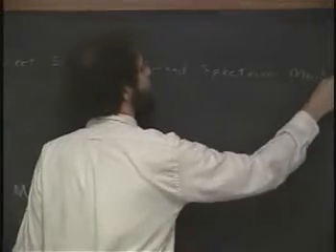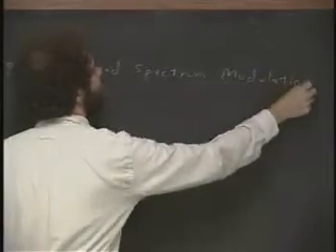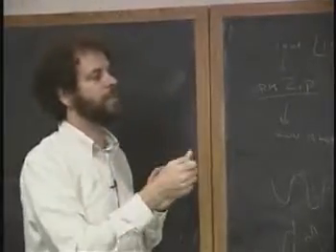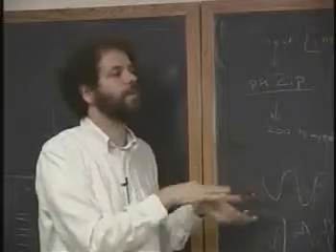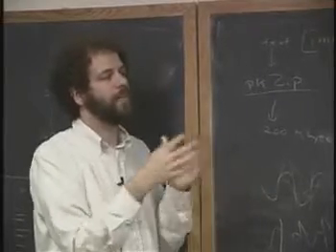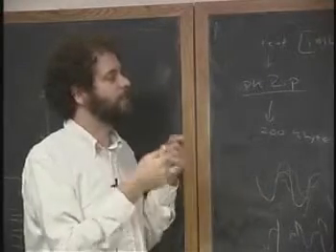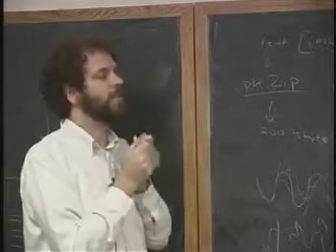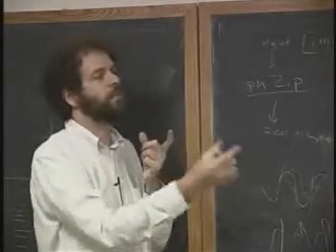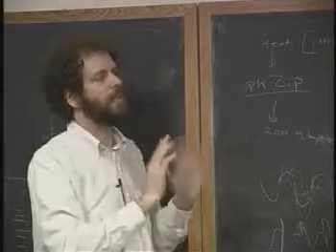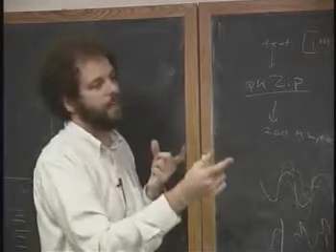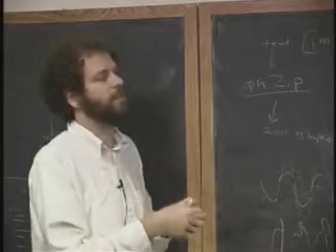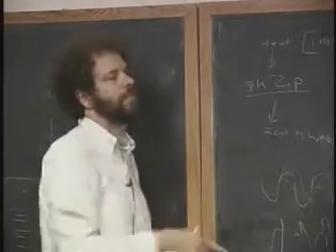modulation. Okay, if you're excited about this stuff, you'll find out that in fact, as long as the receiver and the transmitter agree on the code, okay, and of course, you know, why is one white noise to one person and data to the other? And the answer is that if you and I agree on the code, then I can just begin to transmit, and you can synchronize to where you are in the code without me having to send anything else. Okay, you try to sync up. If it doesn't work, you sort of slip one bit. You try again and slip a little bit, and there's all kinds of methods for doing it without having to go back to this stuff.